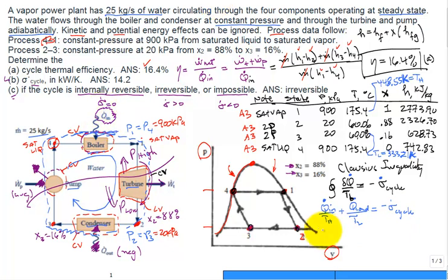Well, it's going to be the mass flow rate times the change in the enthalpy, H1 minus H4. That'll be the Q dot M, and I divide by the TH. Okay, this one I know it needs to be negative, or you just let the math work itself out.